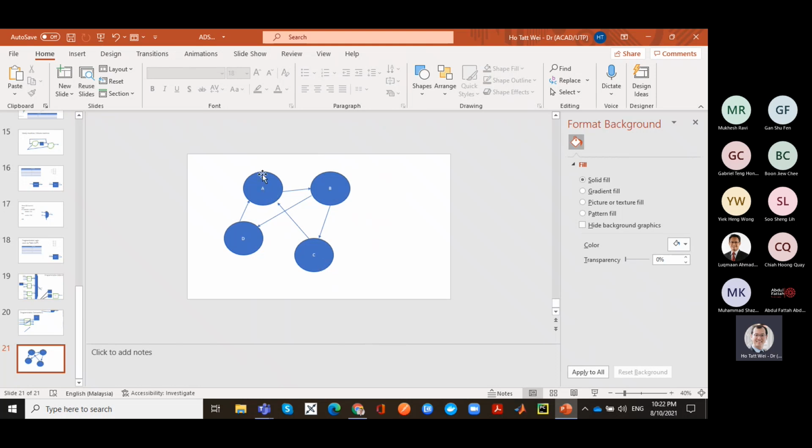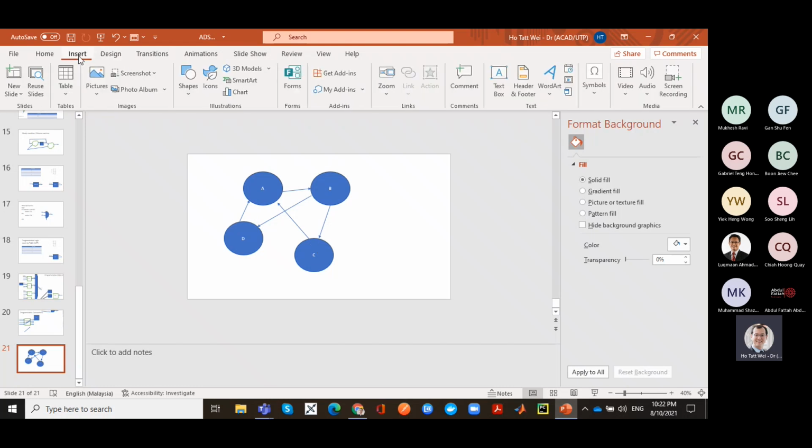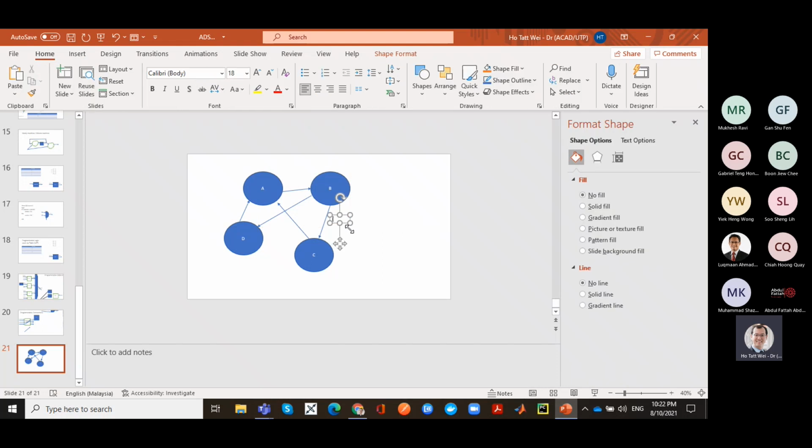If you look at it this way, this state transition is saying that on the first clock, perhaps I start with state A, then at the next clock cycle I go to state B. And what happens in the clock cycle after that? Well, it's a bit confusing because you have two possible routes. You can go to C or D. When you have two possible routes, that tells me the transition must happen dependent on some input.